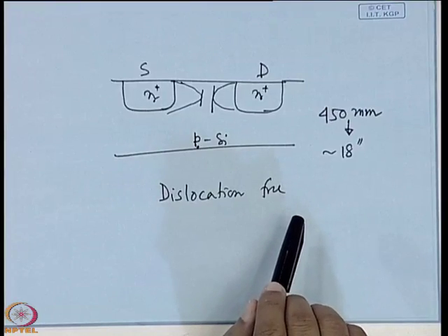If the diameter becomes large, there is a possibility of dislocation, because you can take care of a small thing, but if it becomes larger, you cannot expect the same care can be taken on the whole material. So not only do you need very large diameter material with very high purity, 10 N or 11 N, at the same time you need dislocation-free material.